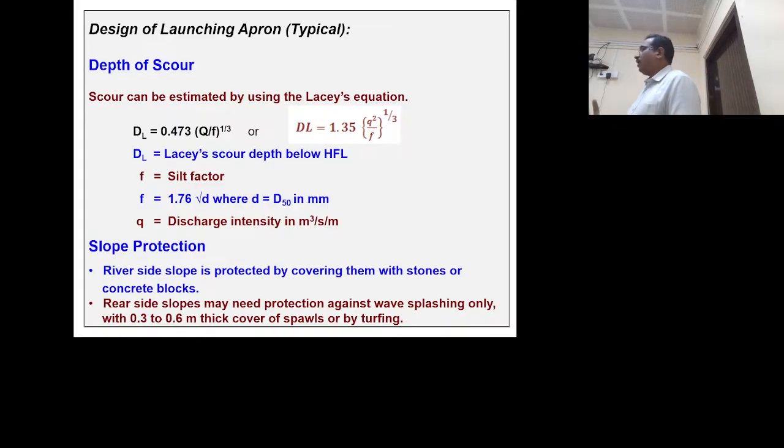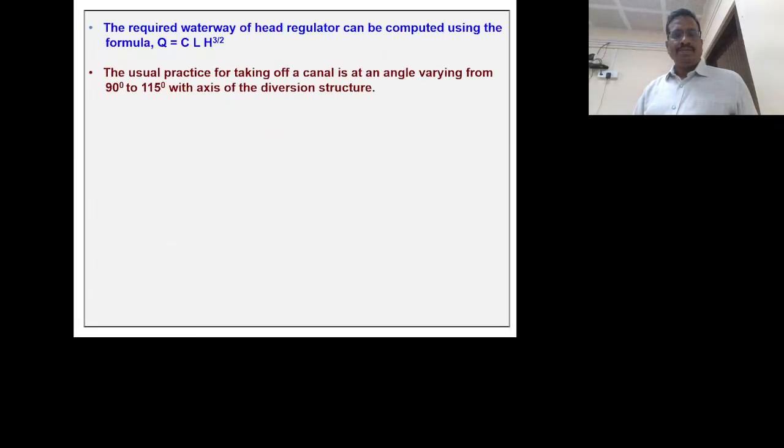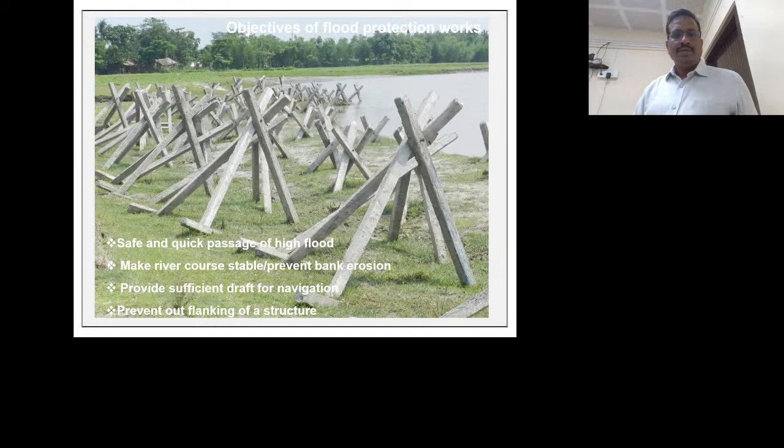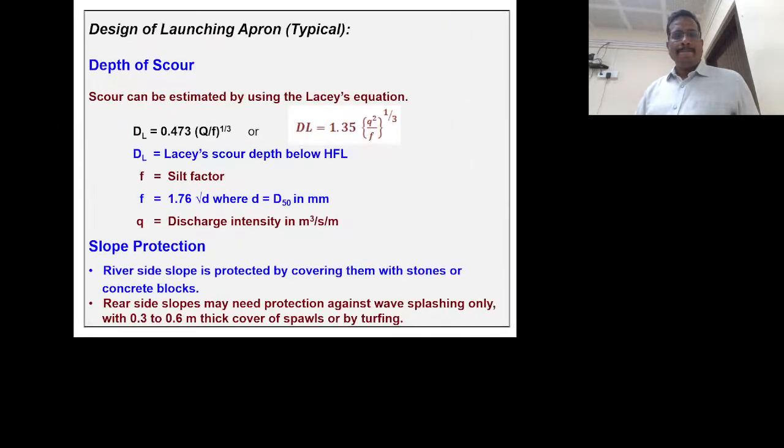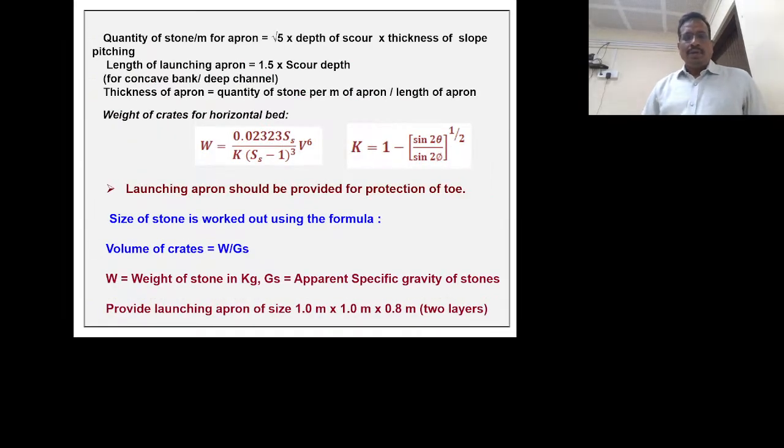What is the meaning of this? The boulders which we have designed should be safe and should not move while the maximum discharge flow is hitting the protection works. It should protect the guide bund or spur, any hydraulic structure. Like that we are calculating, and volume also, as I just explained for the sloping portion, is also calculated in the launching apron portion.